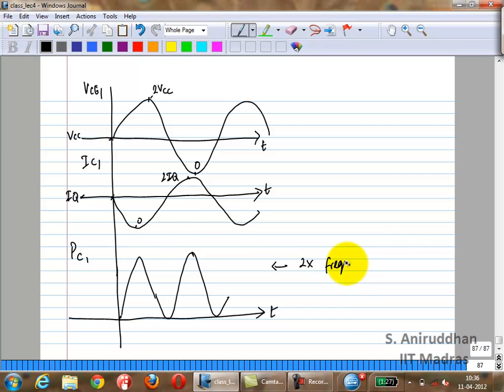So now, as far as the transistor is concerned, why are we talking about the power dissipated in the transistor? That's the losses, but that's okay. Yeah, so losses is one part. We have already calculated the efficiency. What else is there? You have to worry about the reliability of the transistor, right? So as far as the reliability is concerned, you have to worry about the junctions heating up because you have too much current. So this is basically power dissipated as heat in the transistor.